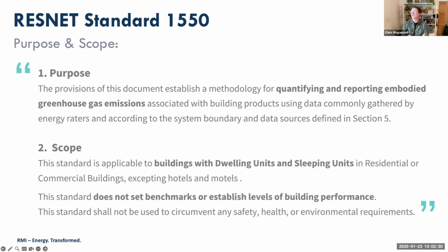Yeah. I would tend to give the target in terms of intensity per square meter, because part of that 16 tons was a very small house. So obviously even if that house used all the same materials but was twice as big, it would be 30. Out of the 1,000 houses that we've modeled so far, 200 kilograms of emissions per square meter has been the average. So anything you can do that's better than that is good.